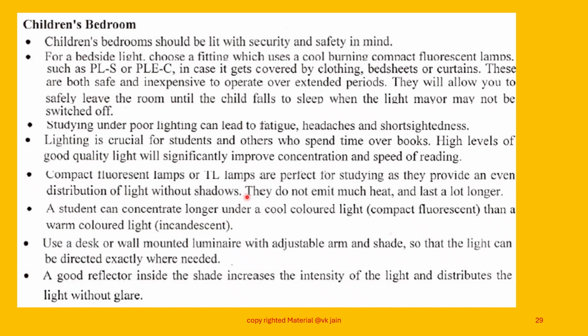They don't emit much heat and last longer. A student can concentrate longer under a cool colored light, compact fluorescent, than a warm colored light given by an incandescent lamp. Use a desk or wall mounted luminaire with adjustable arm and shade so that light can be directed exactly where needed. A good reflector inside this shade increases the intensity of light and distributes the light without glare.